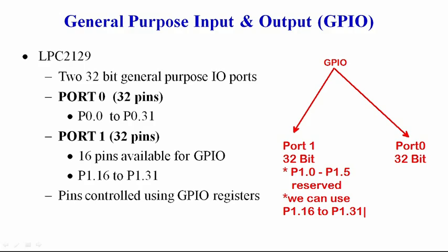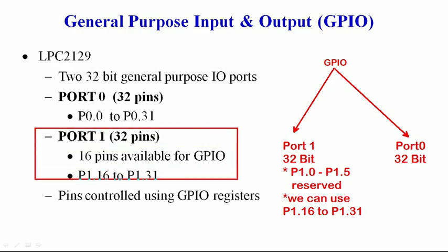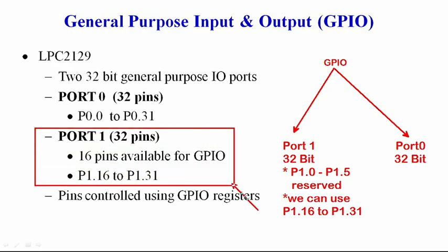So only 16 pins are available in your port 1. This is the point I want to highlight here. We can use P1.16 to P1.31.